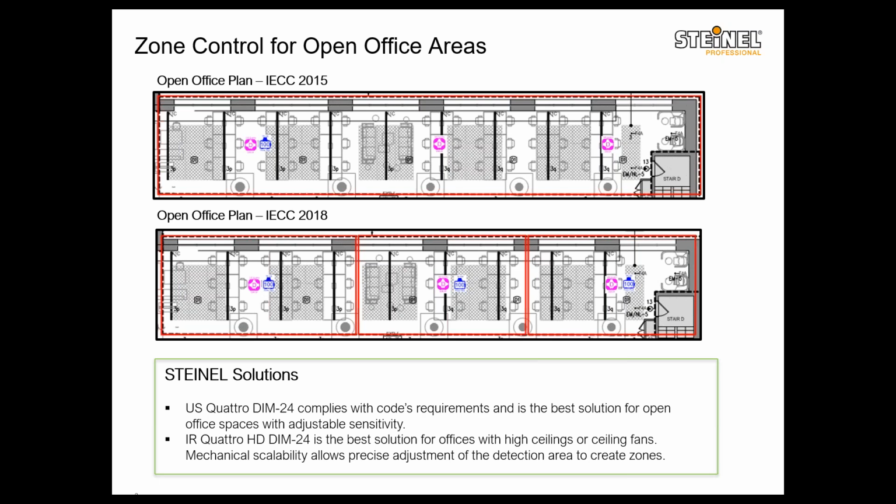So how do we adapt these sensors to only detect within their own respective zones? With our US and dual-tech sensors, we have a dial on the back, or you can adjust the reach of the ultrasonic through the app on the smart remote to make sure that each sensor is only looking within its own zone and is not looking across the zone borders.